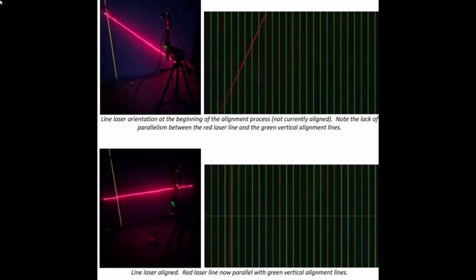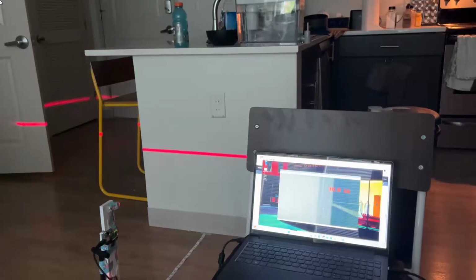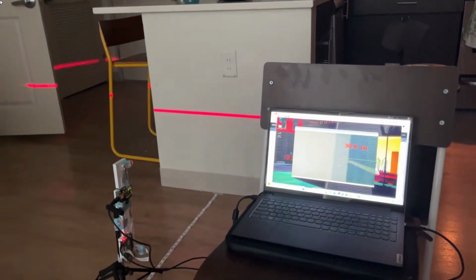To calibrate the sensor, I first performed a horizontal line test by projecting the laser across a flat wall and verifying that the captured laser line appeared level and undistorted in the camera frame. This ensured that the laser and camera were properly aligned and that the system could detect deviations caused by surface depth. Next, I conducted a distance validation test.